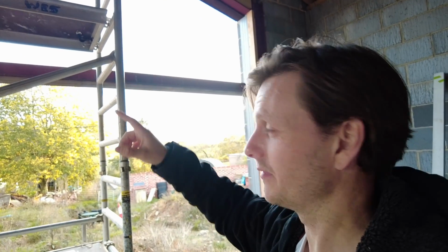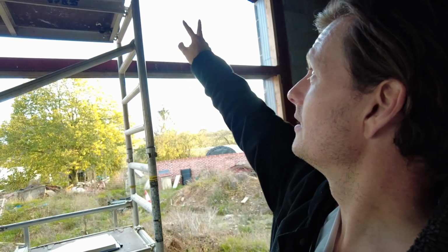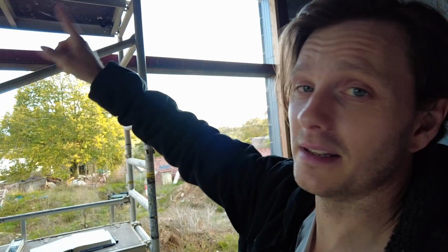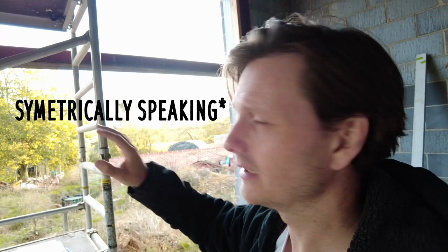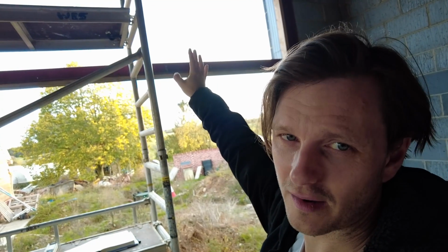So more than likely their technical department could sort it out for you, but do you trust them to do the right thing? I wouldn't want these lined up exactly, because that would throw the top off. So what I have ended up doing, I've found a happy medium between the two. Now, each of my panes of glass, between that one, and that one, they're no more than 10 mil difference between each other. The center mullion effectively is 20 mil off. That one is going to be 5 mil off, and then that one is going to be about 15 mil off.